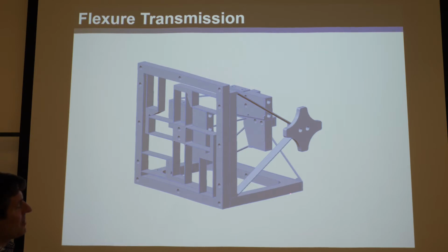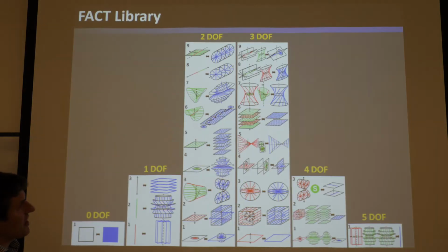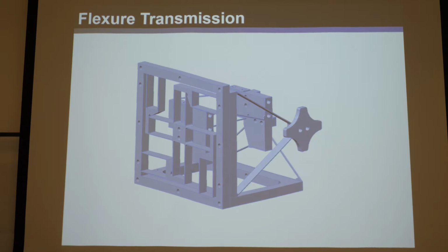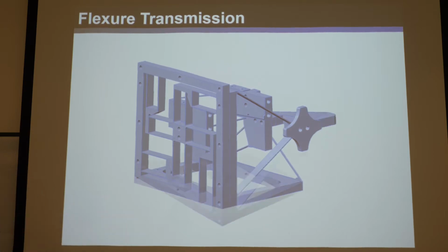This is all ground. And put these intersecting flexure blades that, of course, over-constrain, but they lie in these intersecting planes, and so they achieve this rotation. So at least those are flexure bearings that will constrain that so it can't move in any way but rotate. And then here's the magic. We're going to add this.